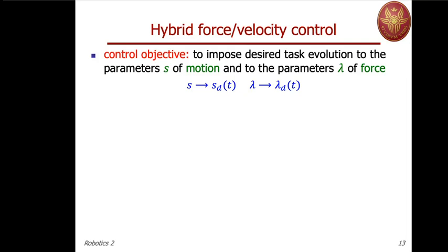If we are able to achieve this by feedback linearization, the error behaves with linear dynamics, and the convergence would be specified, exponential and not just asymptotic. We have already in our background this type of concept, so I will not insist on that. Now, in fact, we will design the hybrid force velocity control using feedback linearization. So, again, in two steps.